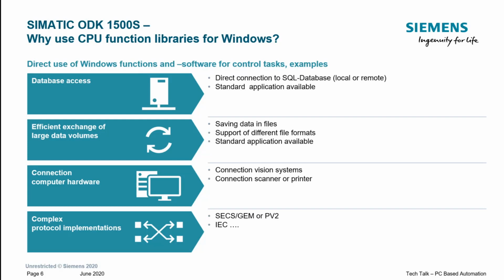Alternatively, with a hardware PLC, we'd be writing it to the MC card, and obviously that's going to reduce its life and fill it up quite quick. So these software controllers are great for this high-speed data logging. We can read the data in at very high speed, and we can start to write it straight to things like CSV files that live in the Windows environment of the software controller itself.